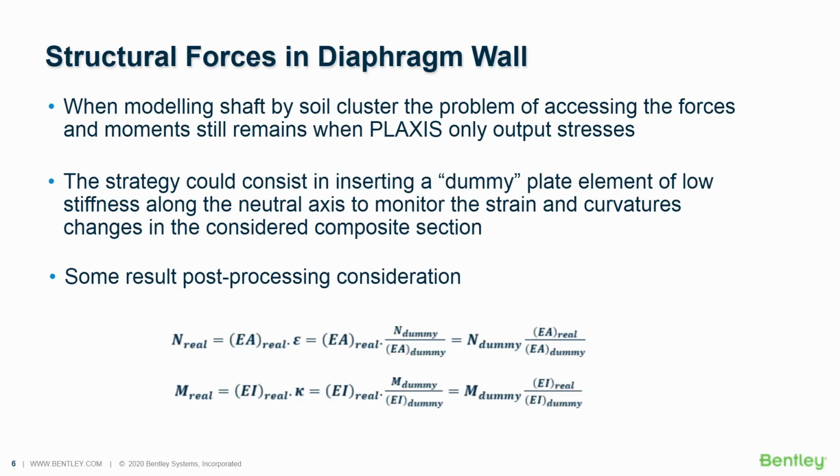This is relatively accurate, except maybe sometimes for the shear forces. And this would require as well that you specify enough elements through the thickness. This is also why I highlighted earlier a recommendation for increasing the number of elements through the thickness of the retaining wall. There is another technique which I'm still using myself personally from the old time, which consists of introducing a dummy beam, the dummy plate, I should say.